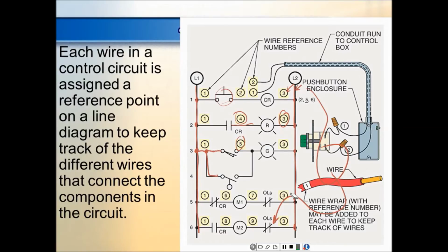Luckily, your car don't use wire numbers. What does your car use? It uses color codes. So they got thousands of color codes. And every time it goes through a connector, follow it out. You'll see it comes in here, it might be green and red stripe, and you come over here on the other side of the connector, it'll have a different color code. Because it goes to a different connector. So cars don't use wire numbers, but they use a color code to identify the wires. And so when you buy the prints, that's what it does, it gives you colors.